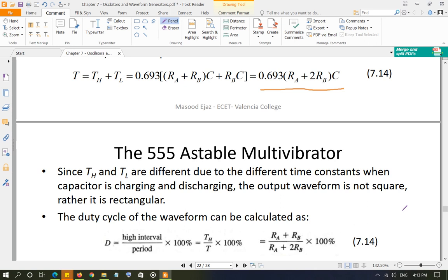Now when you're using an ideal diode, of course we consider that when the diode is on, there is no voltage drop across the diode. Also, when the diode is on, the on resistance is 0. Now remember, ideal diodes do not exist in reality. In practical life, of course, there is usually a voltage drop across the diode when it is on, 0.7 or 0.3 based on what type of diode you're using. And of course there is some on resistance as well, which is quite small though.